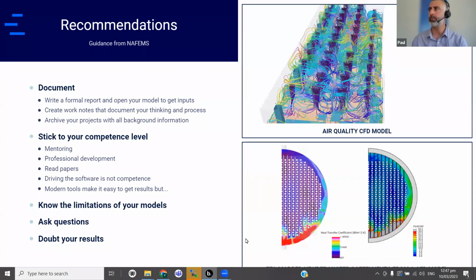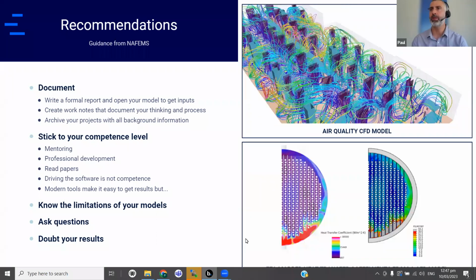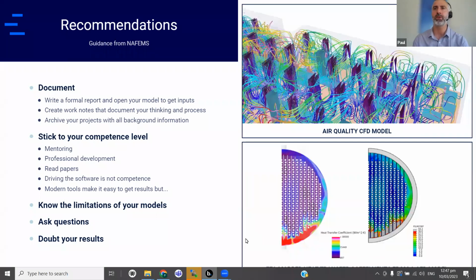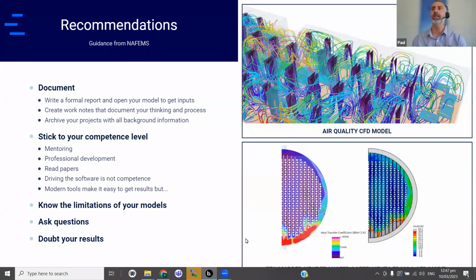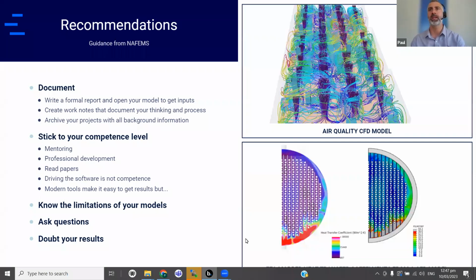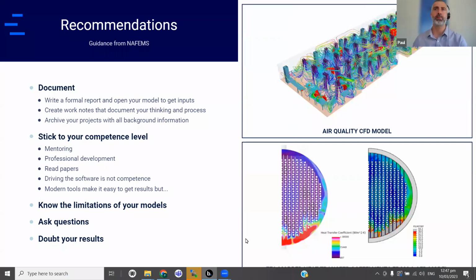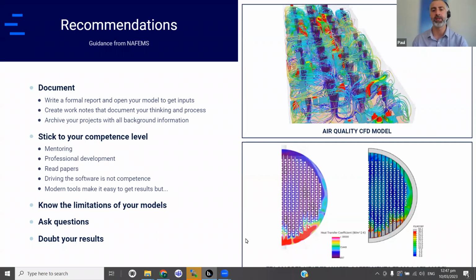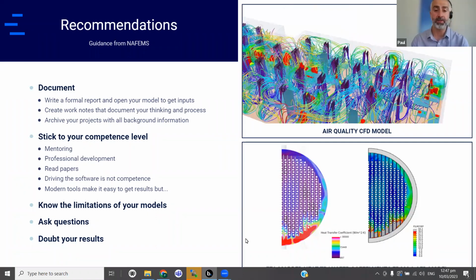There are codes available that allow you to develop temperature dependent material properties, and those codes generally are conservative. So sometimes it's important to understand, if you have a data set that doesn't come from a code, then maybe compare it against a more conservative data set, just to make sure that what you're doing is conservative to the best of your ability, right? So I think that's it.